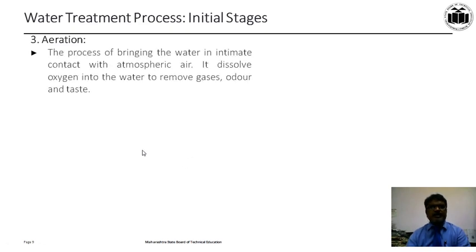Next process is aeration. Aeration is the process of bringing the water into intimate contact with atmospheric air. When the water comes in contact with atmospheric air, the oxygen present in the atmosphere gets dissolved into the water, and the dissolved oxygen content increases.